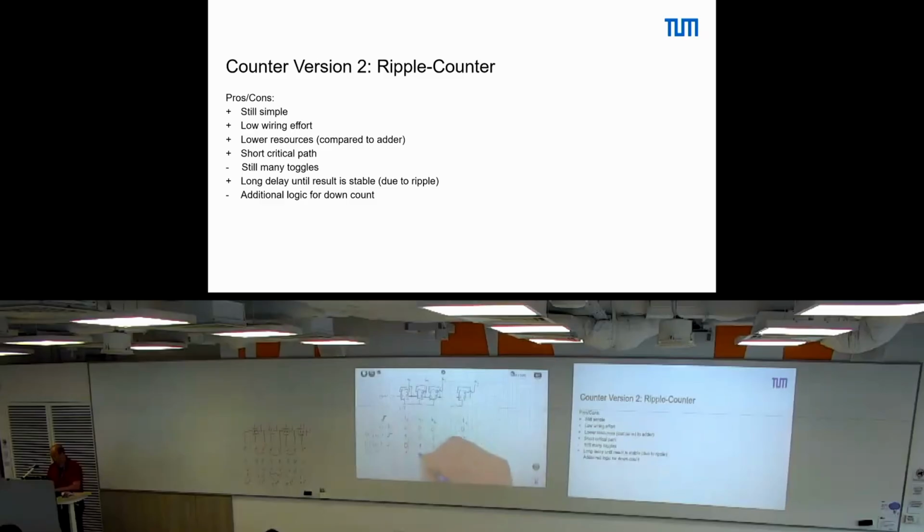Nothing happens to the next flip-flop, so this stays. Fourth, we have a 1 here, a 0 here, because we toggle. Q bar goes from 0 to 1. So Q is 1, so Q bar is 0. If we toggle, we go here from 0 to 1. So this here becomes another 0. Since this goes from 0 to 1, it toggles the Q bar, the input of the next flip-flop. And we have a 1 here, and so on and so forth.